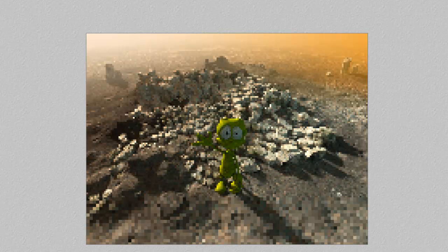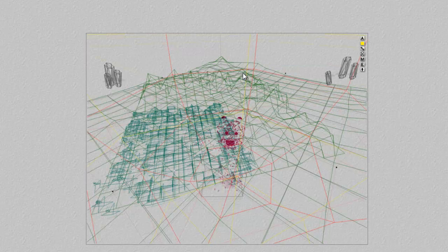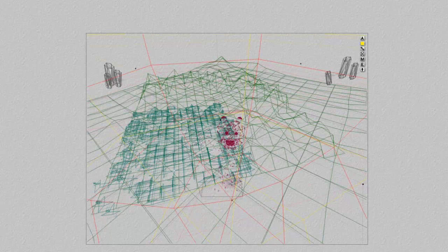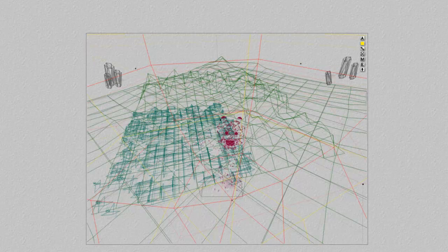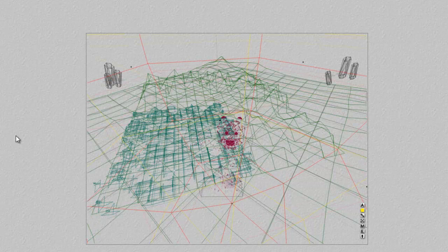And then I've got some light arriving from this side as well to help with the modelling. And then there's this transition zone here, which is where the edge of the sphere is clipping it, but it's just disappearing into the haze. So if I set the size of the sphere down a bit and get a bit more directional light on my scene here, it makes the lighting more interesting and a bit more complex.